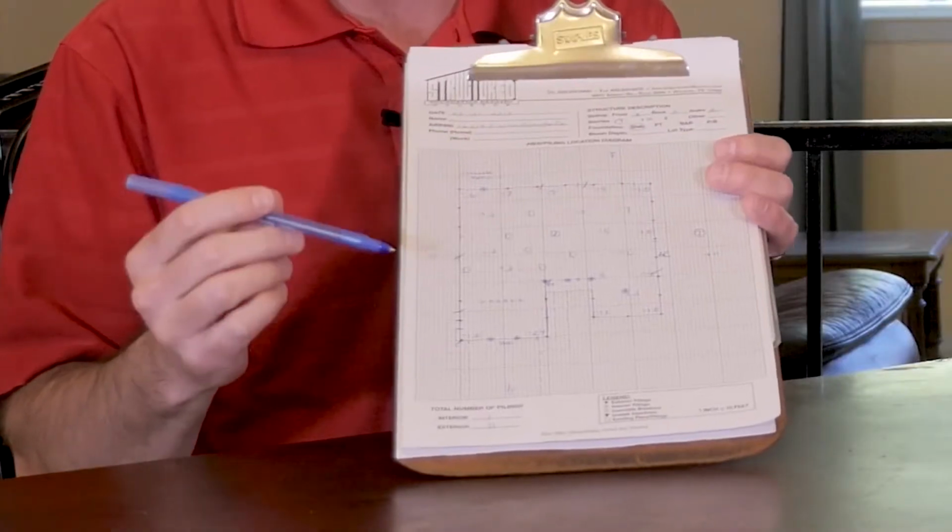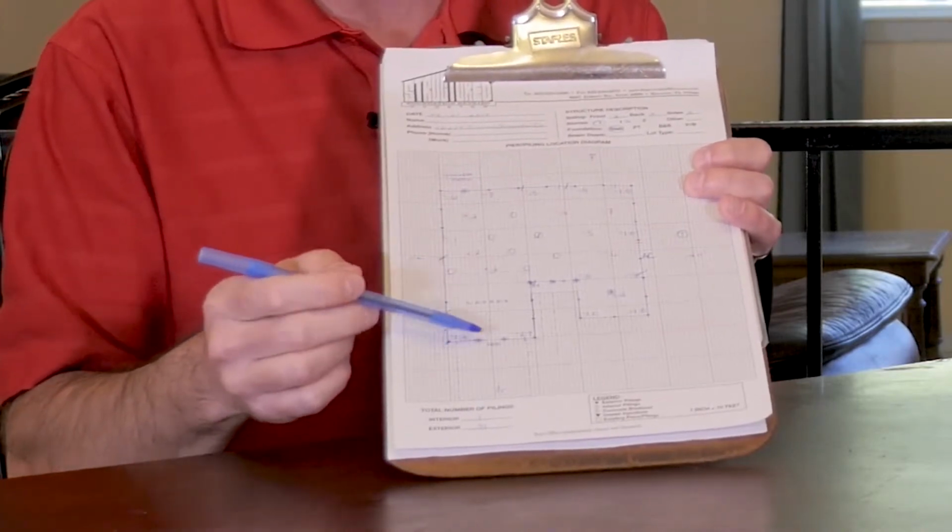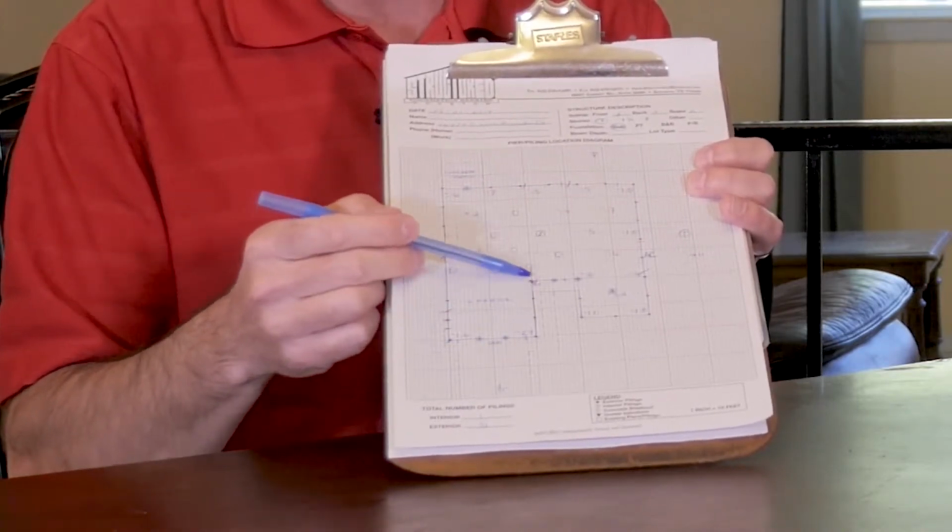So I meet all 3 criteria. I've got deviation, stress to accompany it, numbers beyond that guideline. So I know that I need to repair this slab. I know that I have a problem. And so what we do to repair it, wherever you see a dot on my diagram, represents where we need to place piers underneath the slab.